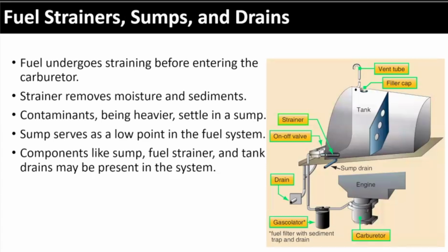If you've got water and sediment there, you've got a little drain here, okay? You're going to drain the fuel from the tanks before every flight. You're going to take a sample and hold it up and say, yep, looks clear, looks blue. I don't see any water sinking in it. I don't see any floaties in there, right? There's no nasties. You know, you're good.